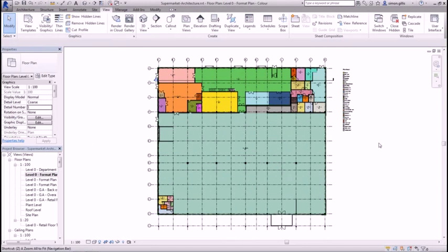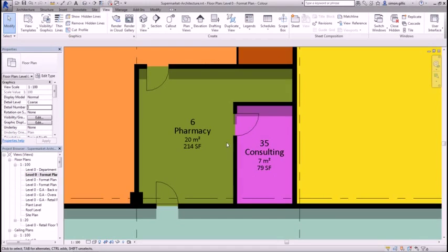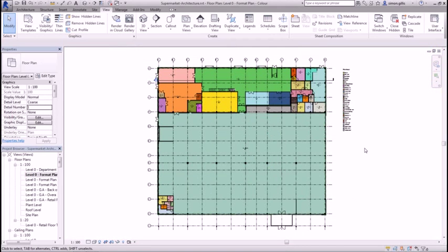If you remember back to earlier in the demonstration, we added this consulting room. Notice it's automatically got a color assigned based on its room name. This really gives us the ability to streamline our process. We're just creating that model element, and how we then view that can be controlled, but it means that we're not spending so much time post-processing to output and improve our visualization. So a really beneficial aspect of Autodesk Revit LT.